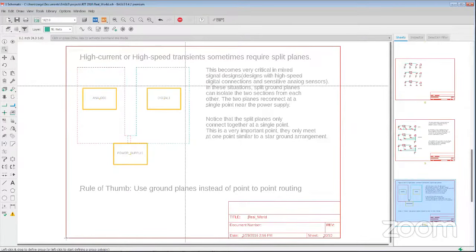What you can do is, if you do the layout carefully in such a way that all the digital is maybe on one side and all the analog is on another, they won't intermix because the return currents are trying to follow the same signal path in order to minimize losses and impedance, because electricity, like water, looks for the path of least resistance, or in the case of a high-speed design, and more generally, the path of least impedance. And that path occurs when the return current can follow the same path through which it came, to the signal path. So if you have a trace going to a component on the top layer, and you have the plane on the bottom, the return current is going to try to follow that trace on the top. It's going to try to be as close to it as it can.